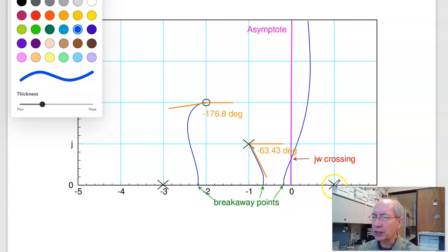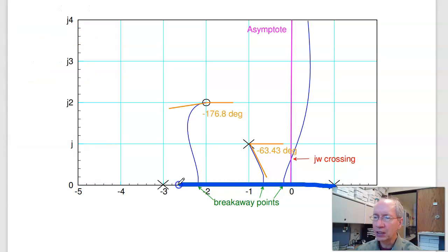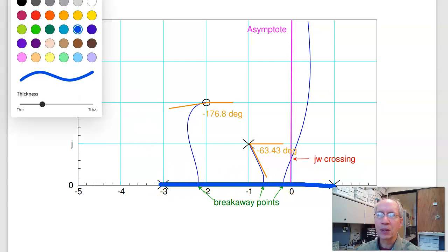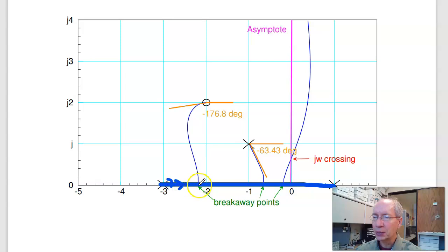So here's even, odd, even. So this is the real axis loci between -1 and -3. The breakaway points are where you leave the real axis. So this pole starts coming right, then splits apart. Here's one breakaway point. This one goes left. This one comes down. One goes left, one goes right. Here's the second breakaway point. There's the third breakaway point.